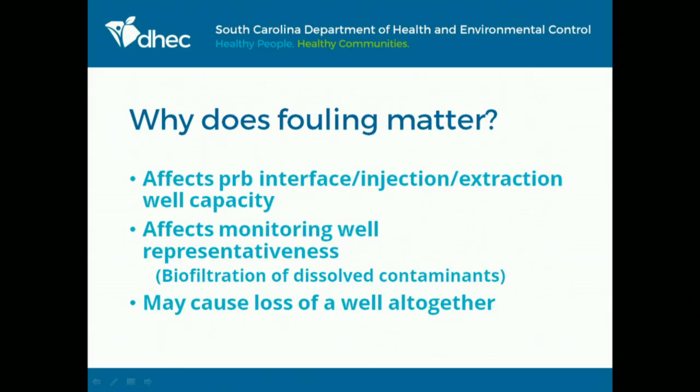Fouling also can affect your monitoring well representativeness. If you have a lot of fouling right around the well screen, then the contamination may be in the aquifer, but as it passes through that biofilm, it's going to be cleaned up. It's going to look like you don't have a problem.